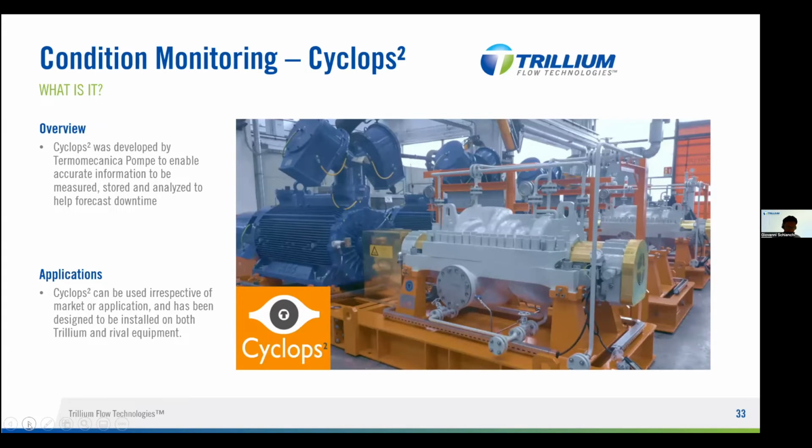mainly with the scope to keep under control the most important functional parameters of the pumps, such as bearing temperatures, vibrations, but also the most important operating parameters, such as suction and discharge pressure, and also flow and velocity and absorbed power.